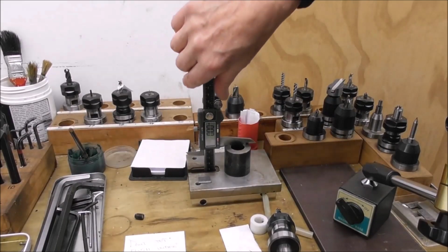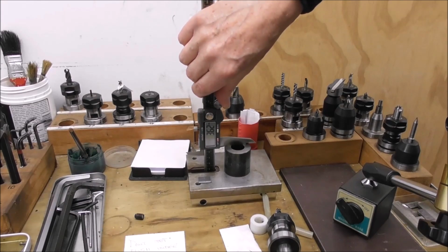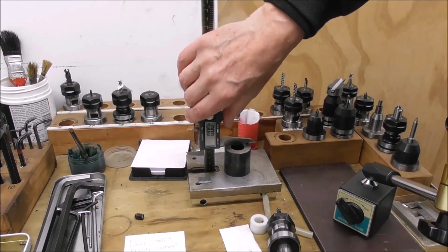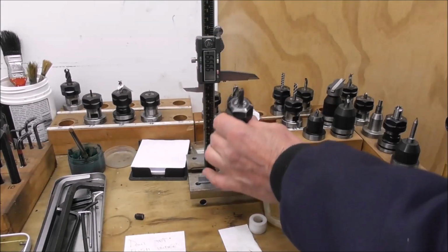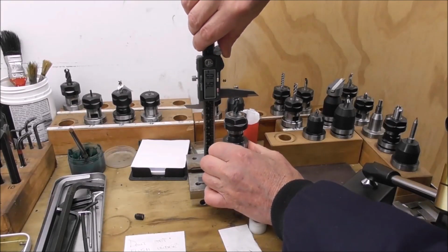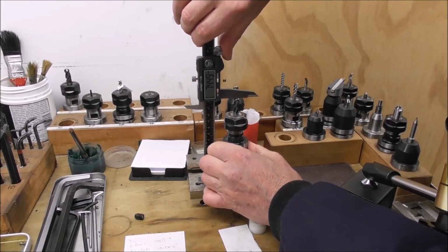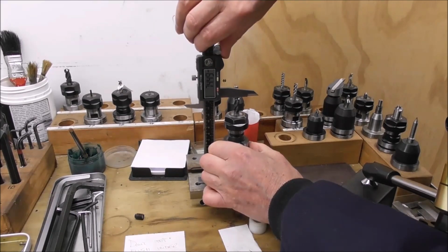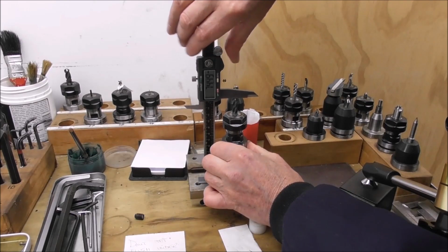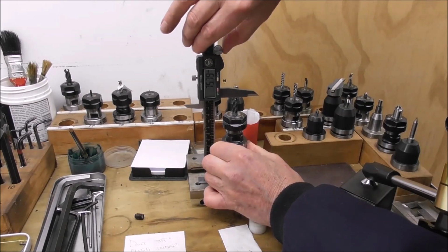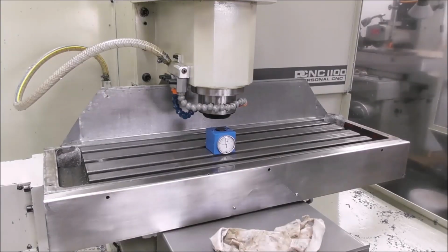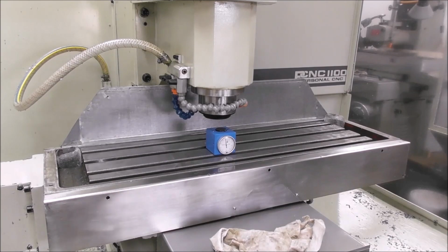Okay, well, let's do a real world example measuring off the machine and on the machine. So we've set our height gauge to 0. We've put in our test tool and we'll measure the height or the length of it. 74.49 across the flutes. 74.49. Okay, remember that number. Okay, well, now we'll measure that tool on the machine.